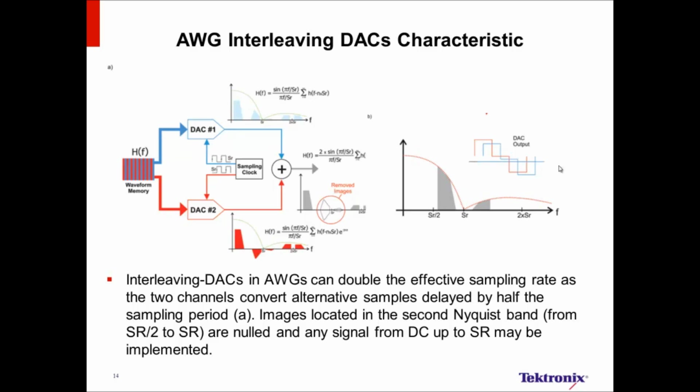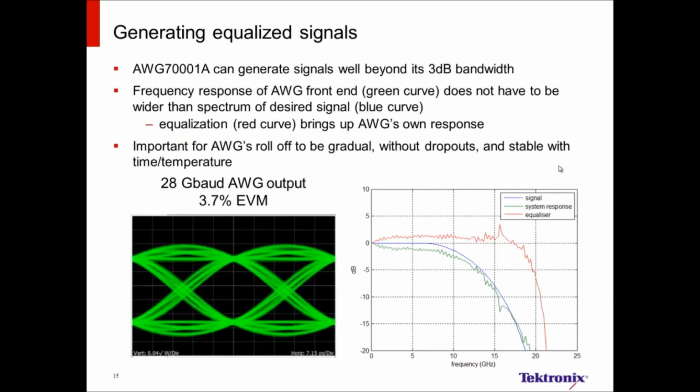But this, in effect, gives us the capability of not having to have a reconstruction filter at the end of the DAC, so that we get a much cleaner system, and you don't have to worry about what the reconstruction filter is going to do. You could build your own reconstruction filter in post-process DSP, but we haven't found that that's necessarily required.